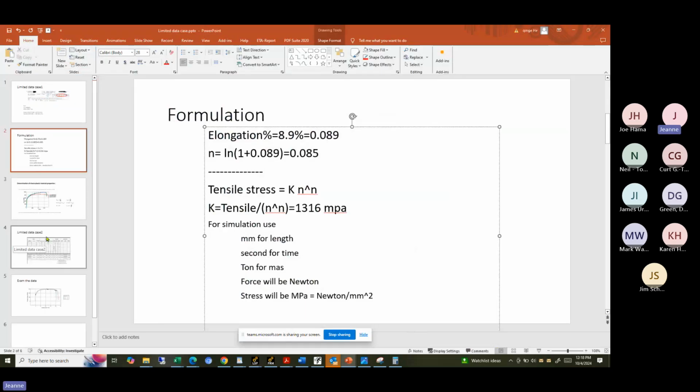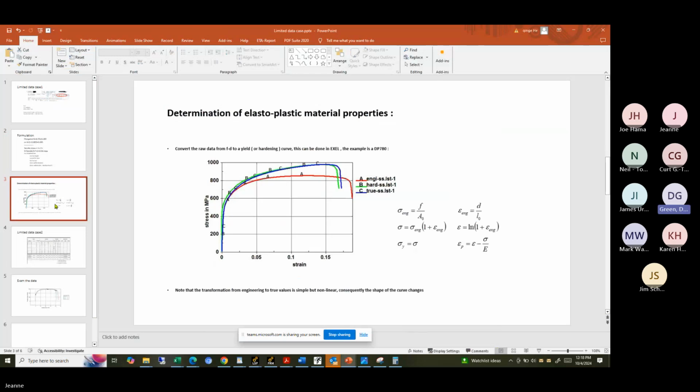Let me see. Or is it that close that it doesn't really matter? Yeah, for yield, the strain is very small, 0.002. So you're right, theoretically I should multiply that stress by pretty much 1.002. So almost the same. Yeah, I just ignored it. Okay, thank you for that. Good points. Anyone else?